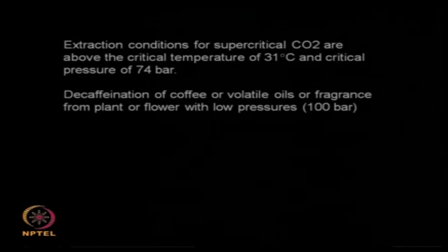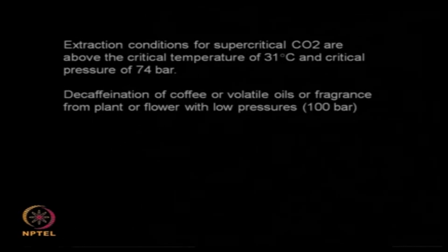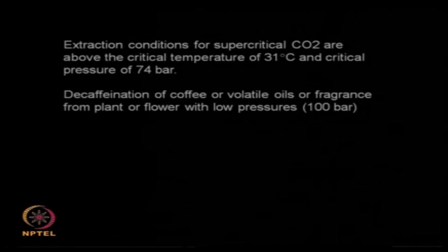For example, if I want to decaffeinate coffee, or if I want to extract volatile oils or fragrance from plant or flower, 100 bar is enough. 100 bar is considered a low pressure. Okay, so at 100 bar and ambient temperature, I can remove the volatile oils and fragrance from flowers and plant material, because here you do not want to increase the temperature, otherwise the fragrant molecules will lose their activity. Similarly, I can decaffeinate coffee at such low pressures.